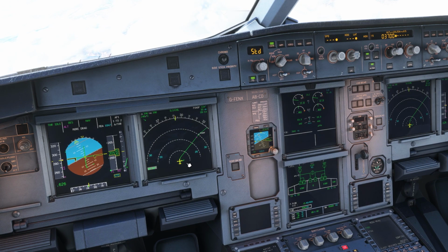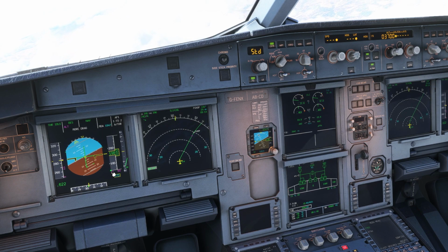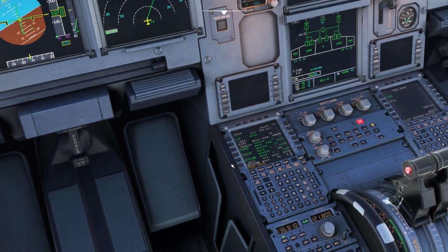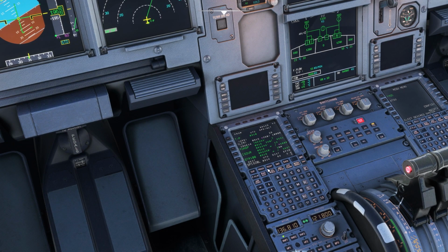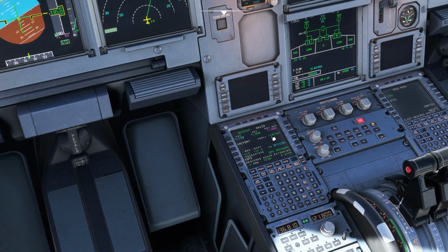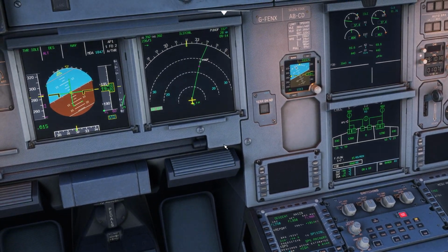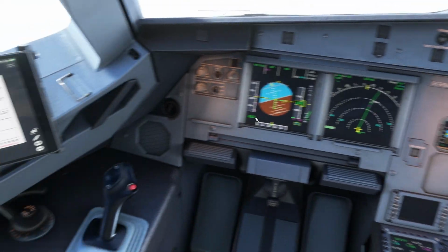Okay, as now I've modified the flight plan, the descent profile was calculated according to that flight plan. Now as the flight plan has changed, that's why the descent profile deviation is very high. And right now how much? If I go here, you can see I'm 1,914 feet above the altitude that I should be at. So I'm at a very high descent profile.